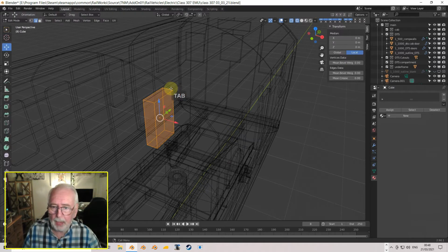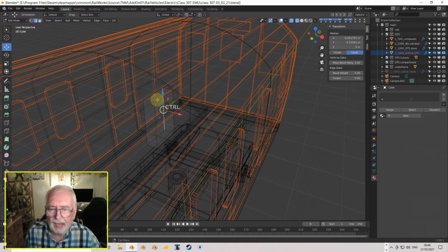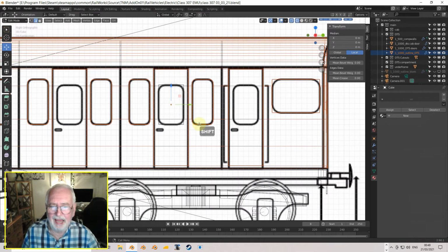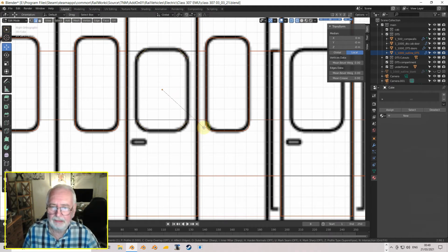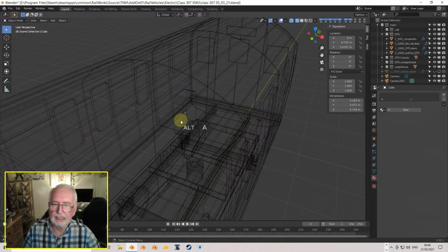So there we go. Let's go back into edit mode, and let's just select those edges. I've got one at the front here I don't want to get off. That's it. Hang on. Let me start again. There we go. And that's it. And front on, don't matter, that's outlined in orange. Front on, and control B, there we go. And just come in, bring the corners in like that, and go 1, 2, 3. Okay, and that's about right. So there we go. There's our cutout. Okay, and let's deselect everything.